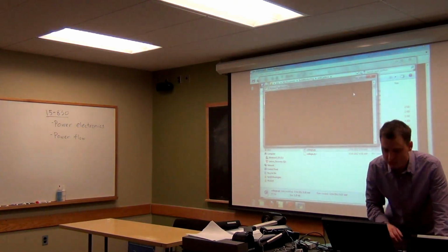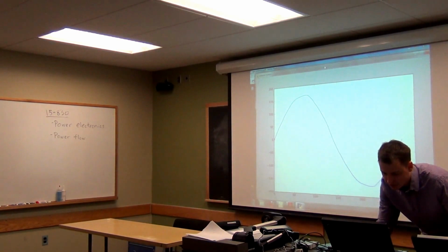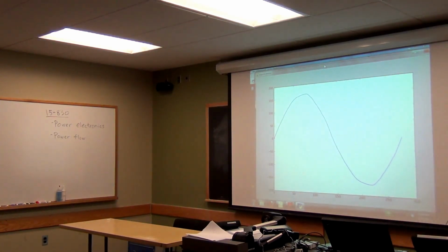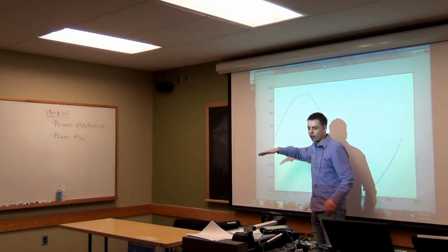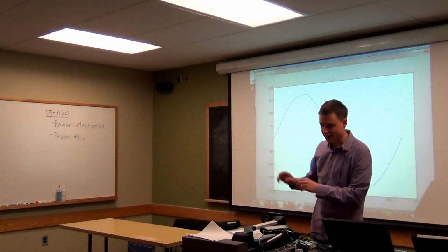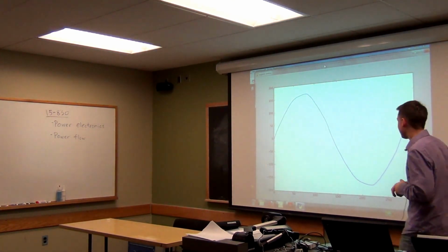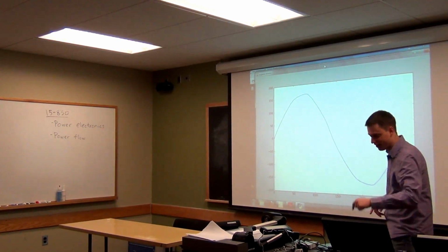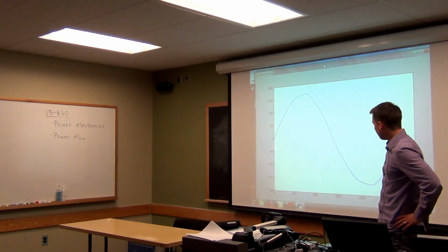So this is going to now plot a picture of the voltage on the scale of voltage itself. There's a little bit of jitter. Don't worry about that. That's really just because I'm looking for the spot where it crosses 0, and it varies by a fraction of a timing step in the resolution of the graph. But this is what the voltage looks like in this circuit right here. Really, all of these circuits, they're all connected. So that's sort of what you expect, right?